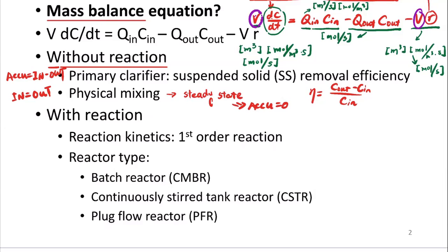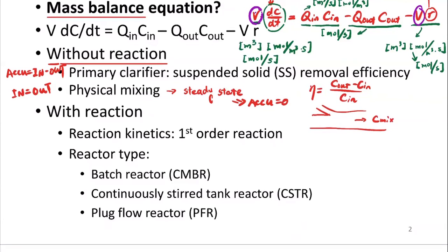So basically the snow melt with the stream water, right? So we have, let's say, a snow melt that has a certain high concentration of the salt, and then we have the stream water which has a very low concentration of the pollutant. Based on this concept, we can calculate what is the concentration of the pollutant within the mixed water, right? So these are the examples that do not involve reactions. So these processes are very simple, right?